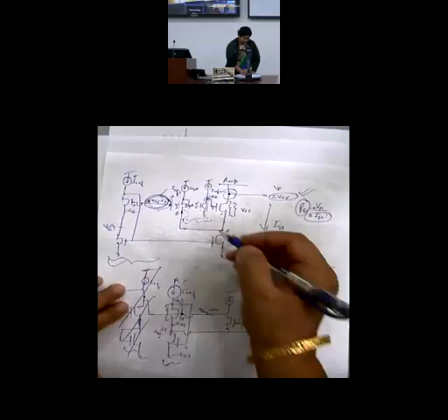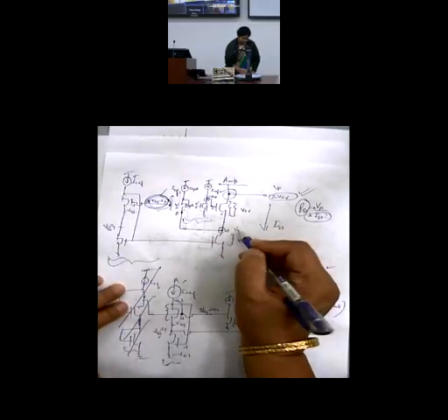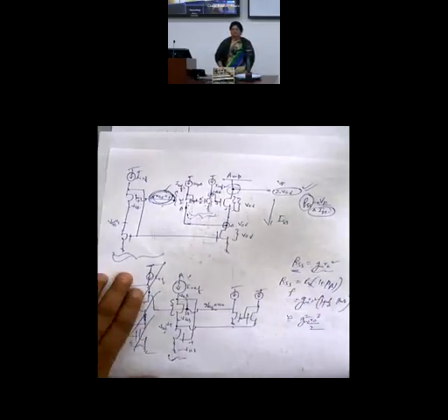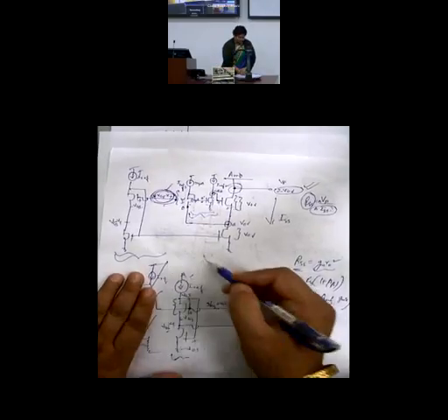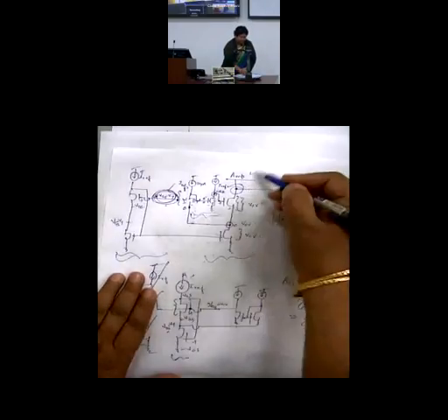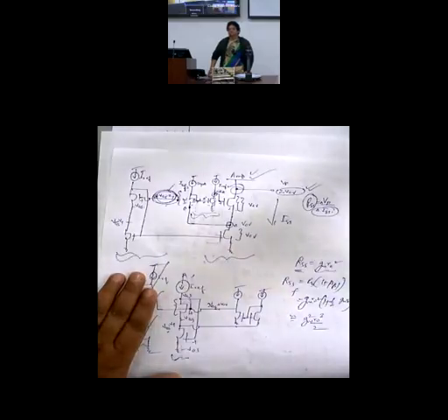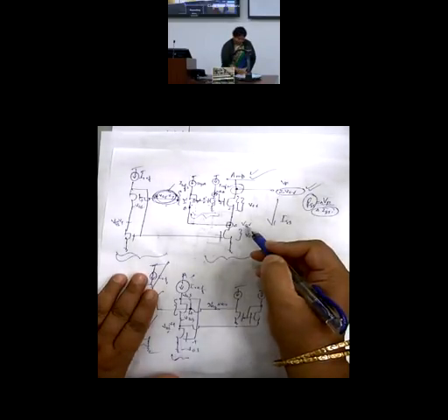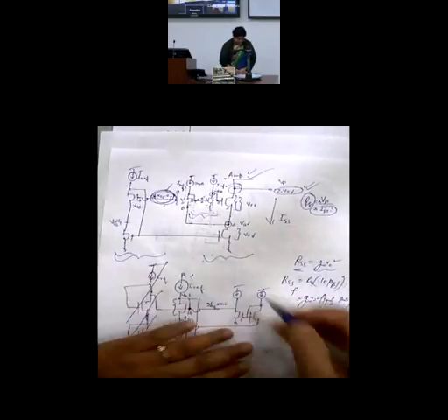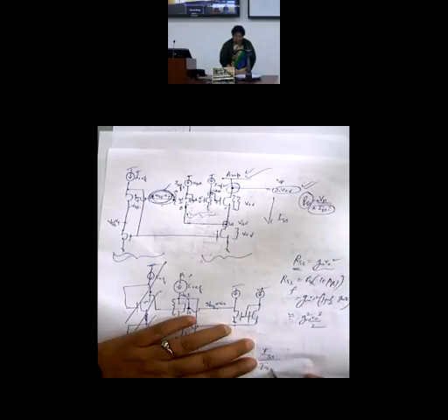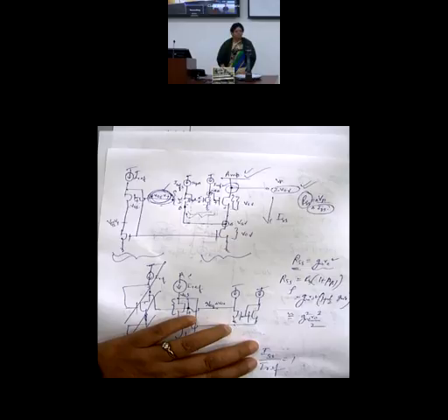So here, this node is coming to 1 V overdrive. This is your biasing arm, which is connected to the amplifier. Clear? If this is 1 V overdrive, and remember, I would be looking at the ratio ISS by IREF in the current mirror. This must be 1, if I am assuming proper matching.